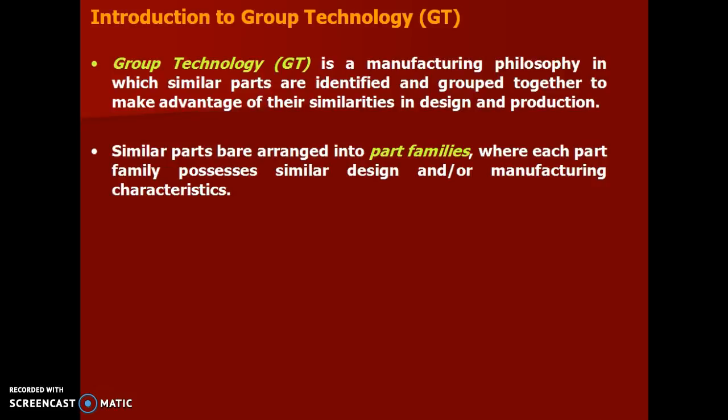Group technology is a manufacturing philosophy in which similar parts are identified and grouped together to take advantage of their similarities in design and production. Here, similar parts are arranged into part families, where each part family possesses similar design or manufacturing characteristics.